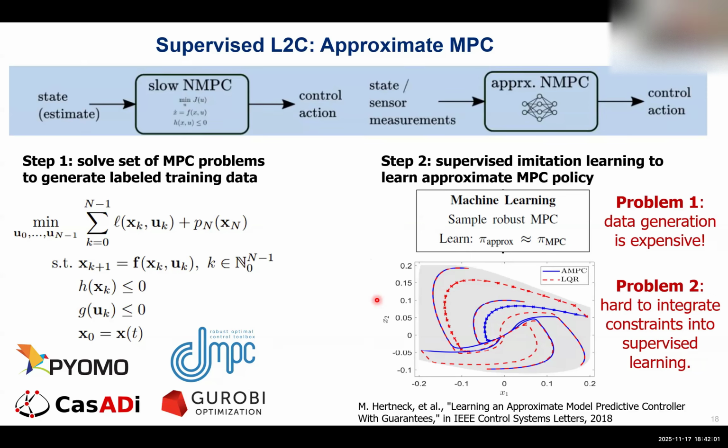Yes, so the curse of dimensionality in explicit MPC comes from your number of decision variables and number of constraints. The reason is that you are using multi-parametric programming to factorize your KKT system. And then in order to construct the polytopic or piecewise affine control feedback law, you are exhaustively enumerating all possible combinations of active constraints.